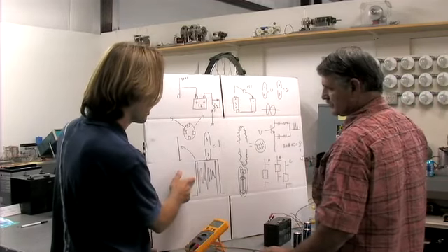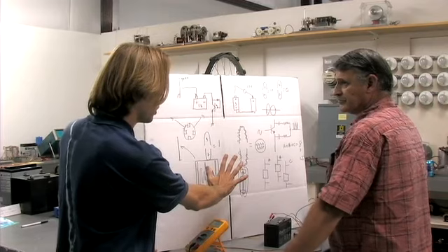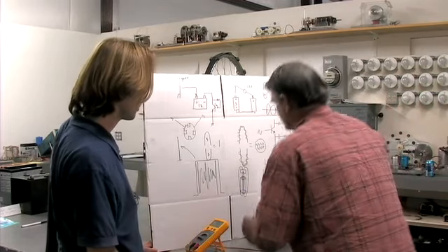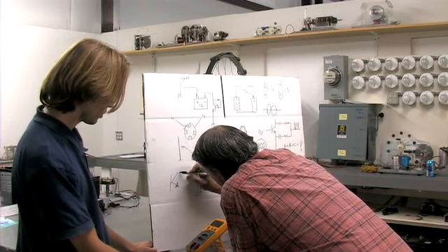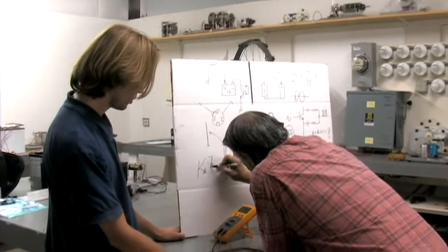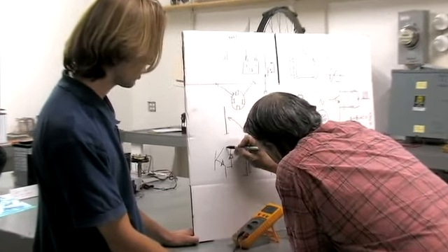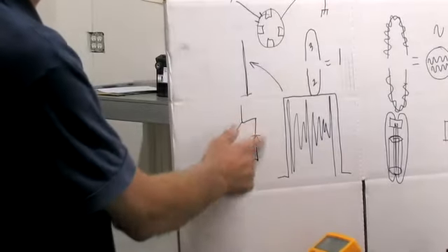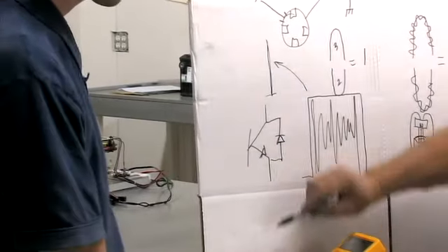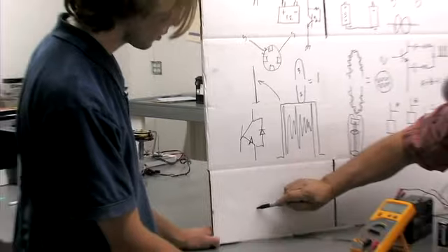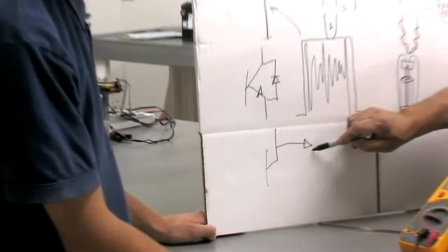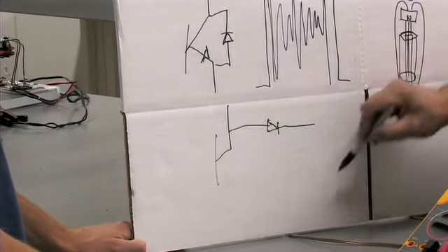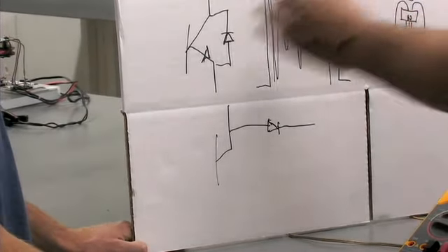So in conventional circuits, that all gets chopped off. Yes, in the conventional circuit, if they see that, they're going to short that out to protect this device. And that's shorted out across. But since I'm taking it off, I'm just catching the spike and sending it to the battery. I don't have to protect anything.